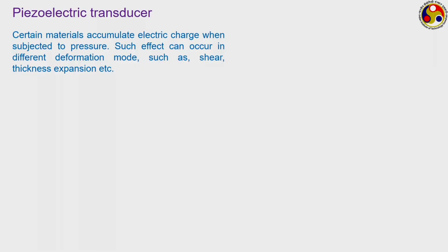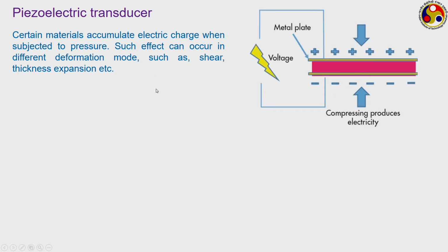The idea of piezoelectricity is that there are certain materials, particularly crystalline materials, that when they are subjected to some kind of pressure, develop electric charge. The effect can occur in different deformation modes, such as shearing action or thickness expansion etc., but the principle is the same.